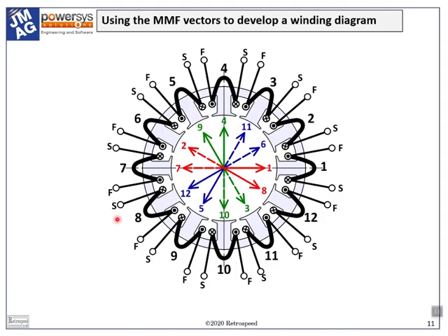We still have to complete the winding diagram. So let's go back to the diagram of primitive unconnected coils and add the star of MMF vectors, which summarizes our decisions about the connections of the coils. Later we will see that the connections can be represented by a connection matrix, but what we need here is a practical winding diagram for the winding shop. So let's translate this into such a diagram, taking the phases one by one. And in fact, we've done everything that we need to do.